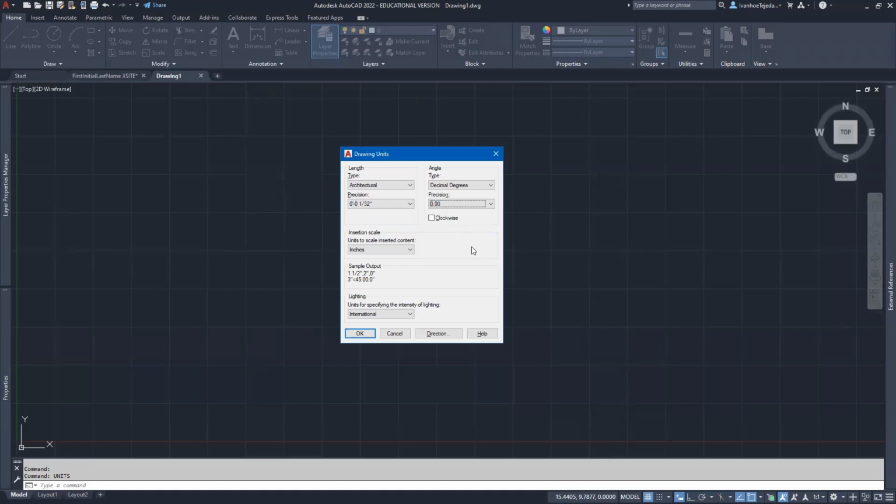But a lot of drawings exist in AutoCAD, and we basically take drawings that we've already drawn before and do a save as. So the units have already been formatted. You're not going to be doing this every single time; you're dealing with existing drawing files a lot of times. I've formatted my length and my angle.